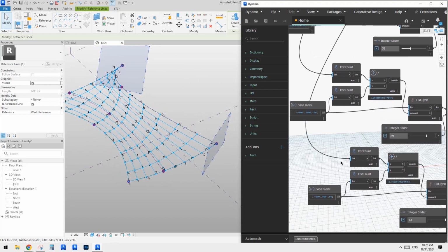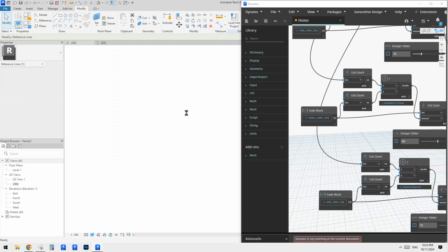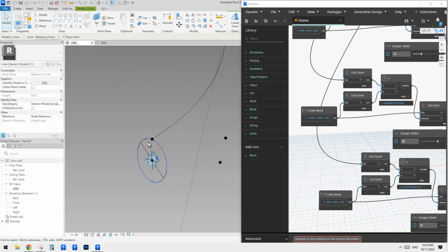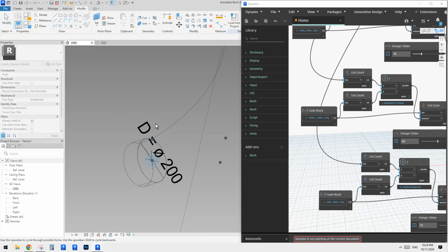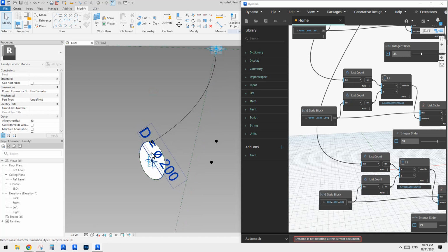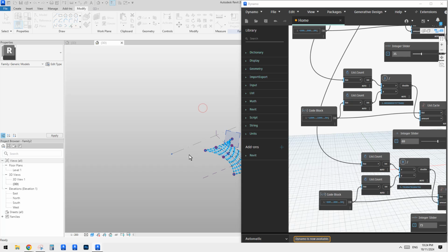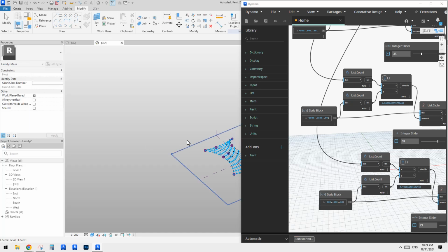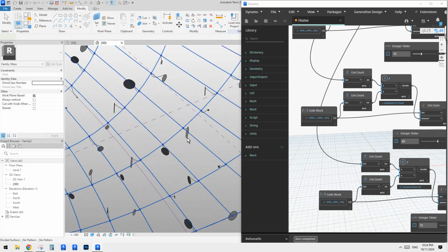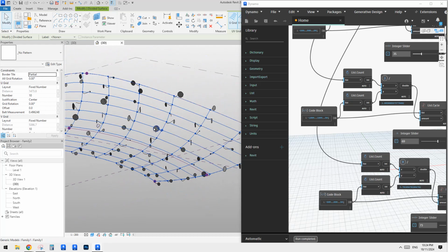Right. So now what I'm going to do is I'll just tick this box to make this a reference line, and then use create form. So you can switch between different options. Use the keyboard, up and down, and place that. Okay, so that's become a surface. Now let's load this one into this mass again, and okay. So now let's have a look. So now they become some surface instead of just lines.